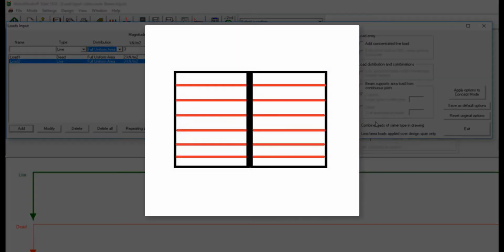Normally, if you use span tables, or even Sizer, the calculation of a beam span is assumed to be based on the tributary length of joists, assuming the joists on each side of the beam are simple spans, that is, discontinuous joists resting on the beam. This would mean that if each joist was 12 feet long, the tributary length would be 6 feet from each joist, and the line load of the beam would be based on the total 12 feet times the area load.